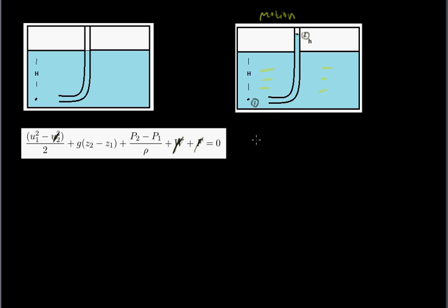Okay, so P1, and this is just like the manometer problems, we just want P1. So that's going to be P2, which is atmospheric pressure, plus the density of the fluid, times the gravitational constant, and times the height. So it is going to be the capital H, because it's only this distance to the atmospheric pressure. It might seem intuitive that you would want to go to H plus lowercase h, but really we just want the height until you get to the surface. So we just want the capital H height.